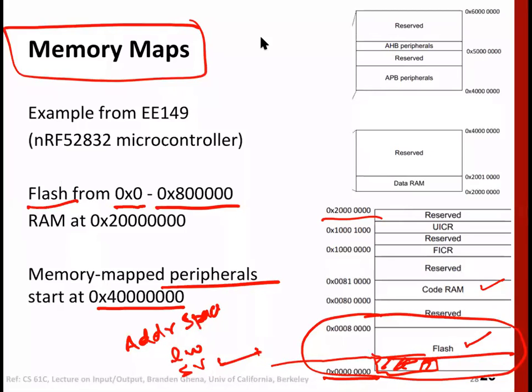This address onwards is for peripherals, say a keyboard or whatever. So once we reserve certain locations or addresses for devices, we can do reading and writing to that device. By read or write instructions, we can read and write the corresponding registers there. So this is at a very top level.